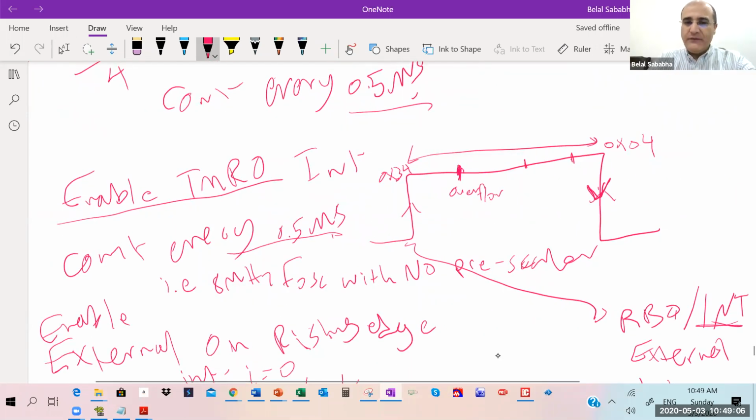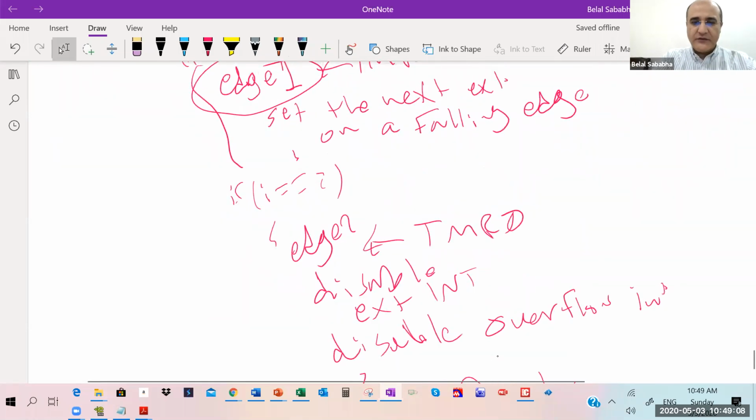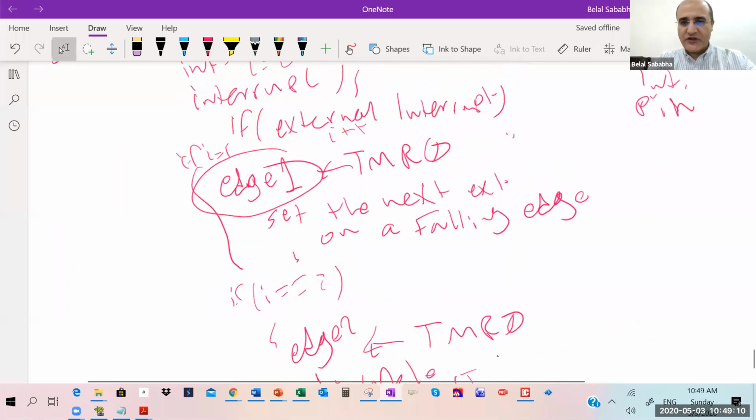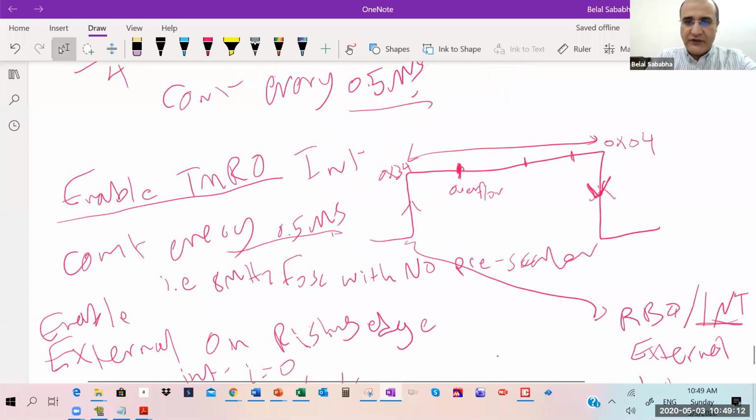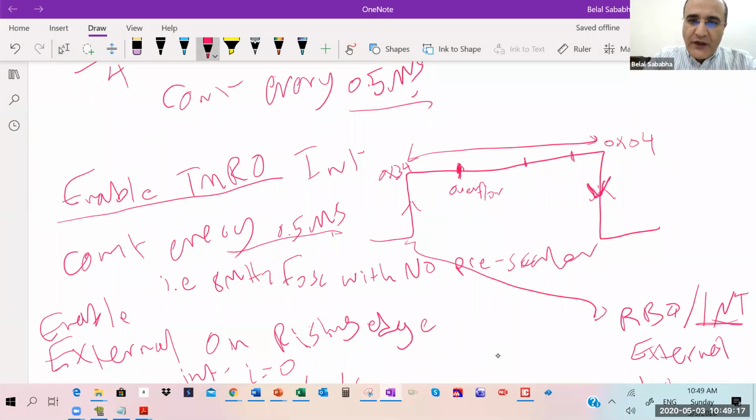So in our example, I wrote the code, and now you're at a level where you can just go and code it in micro C. So I know that an event happened at value 0x34, a rising edge, and a falling edge happened at value 0x04, and I have three overflows in the middle. So what is the time between these two events, the rising edge and falling edge, which is the pulse width?